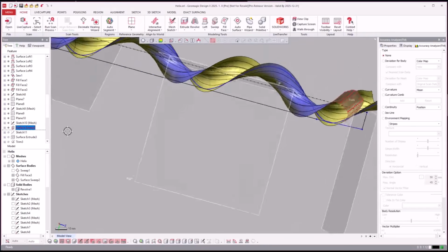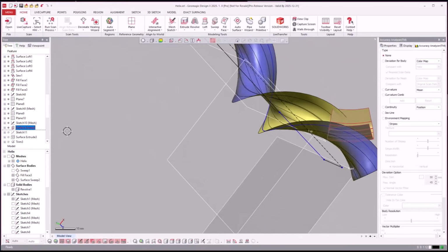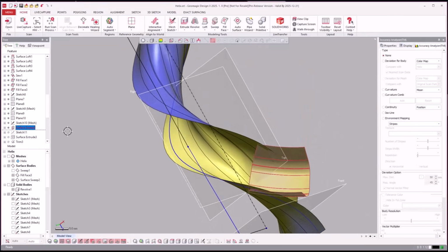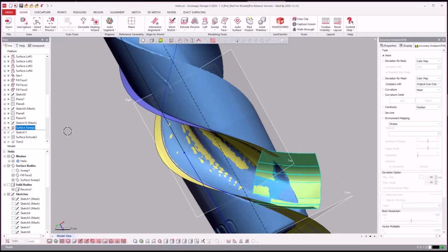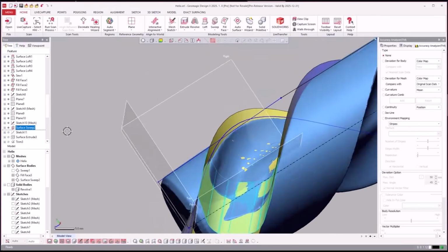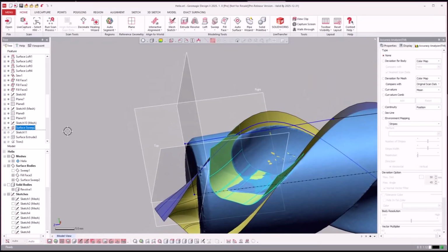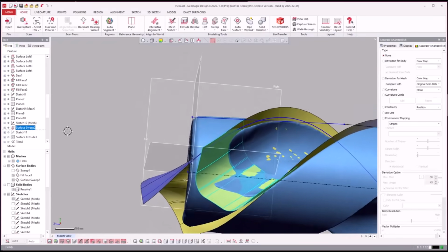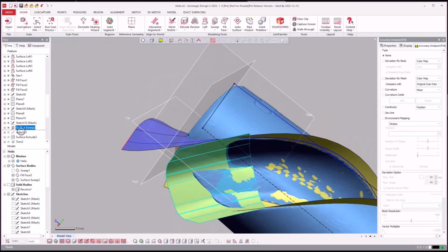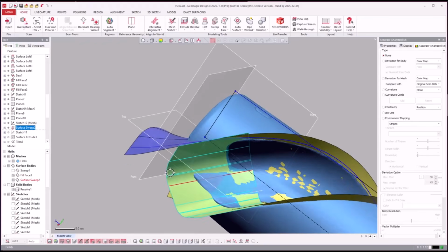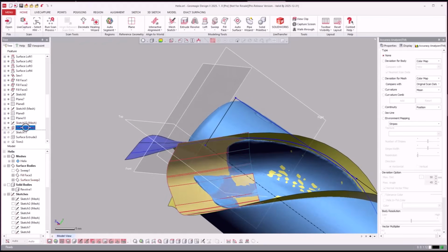Yep. On the other side, it looks like they did a sweep exit. We'll just turn on the mesh so we can kind of see. Instead of doing an extrude exit, they did a sweep along a profile. They drew that sketch down here that had a slight arc to it. So then I swept this profile along that. And then let's come over here.